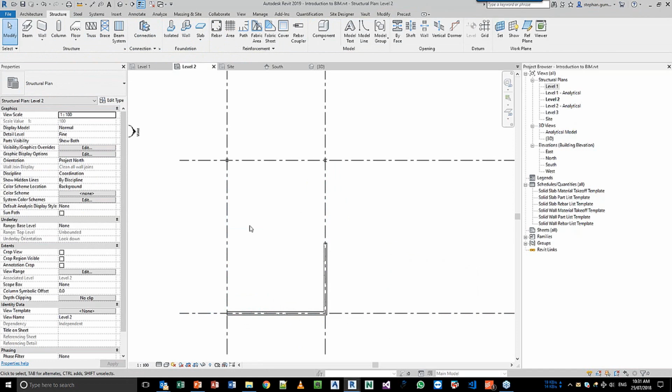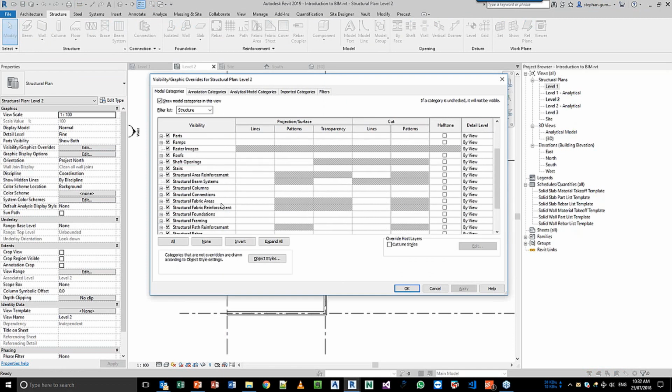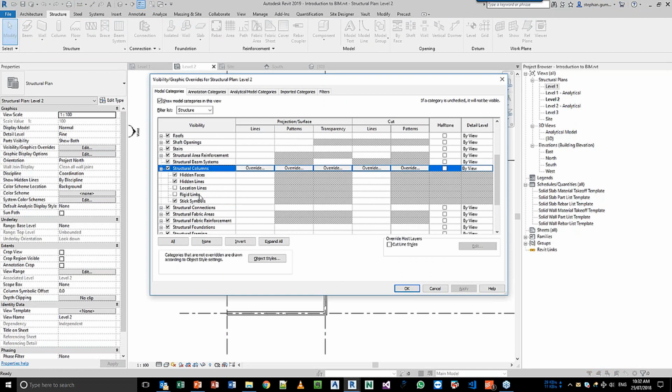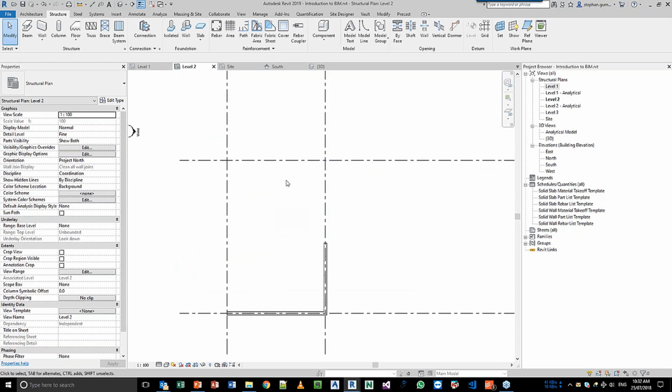Then maybe you can see here that I have 2 different object types. So if I come into my visibility graphics, which I've just hit the key in VG, and let's say, for example, I don't want to see structural columns. So I can actually turn these structural columns off, and you can change the override of how these things are all visible. Hit apply, and when I come back into my model, you can see those structural columns that I placed previously are not visible, right?